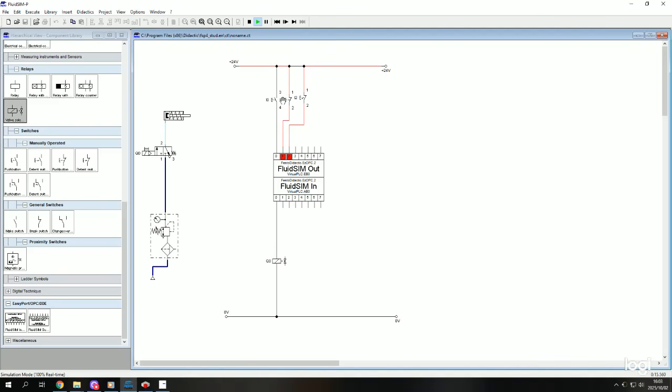I want to show you the difference between the emergency stop and just a stop button. I click my push button, it advances. I click my stop, it retracts. I click again, it advances. Then I'm going to use my emergency stop, which will not enable us to advance our piston rod once again. I click this emergency stop, then this arrow shows that it's been activated.